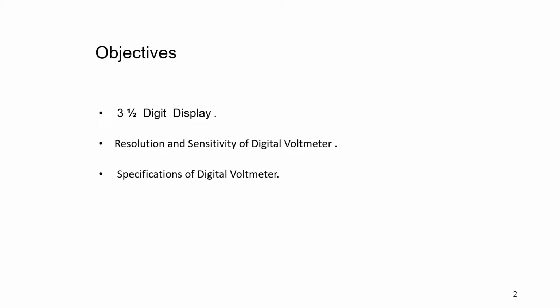The ramp continues until the second comparator circuit senses that the ramp has reached 0 value. The ground comparator compares the ramp with the ground. When the ramp voltage equals 0 or reaches ground potential, the ground comparator generates a stop pulse. The output pulse from this comparator closes the gate. The time duration of the gate opening is proportional to the input voltage value.